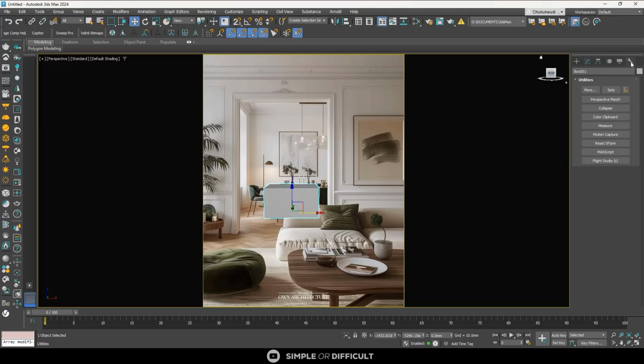In this place, you see this tab. Under here, you're going to see perspective match. So I'm going to click on it. But when you click on it, nothing happens. If you want to bring out the lines you're going to use to align this, you have to come down here and click on it over here. Now, when you click on it over here, it's going to bring out three sets of lines. Each one has two in between, with which you're going to try and match the angles of this. So I'm just going to take this red one.